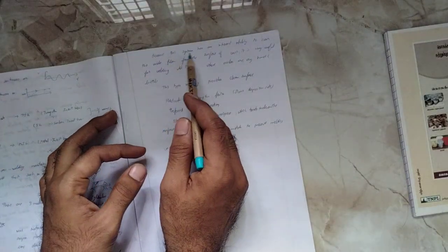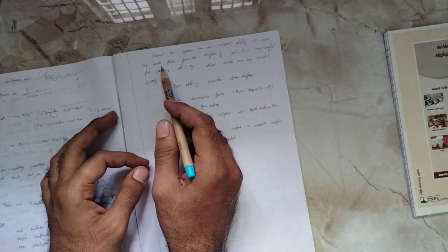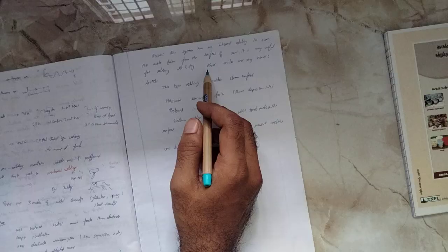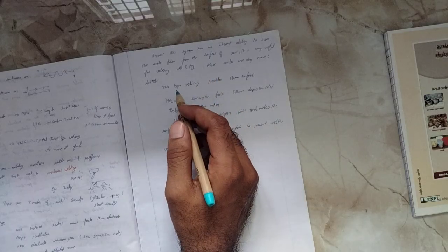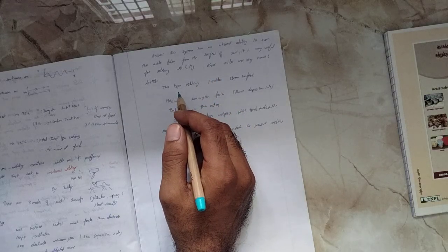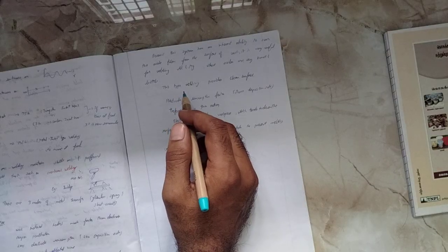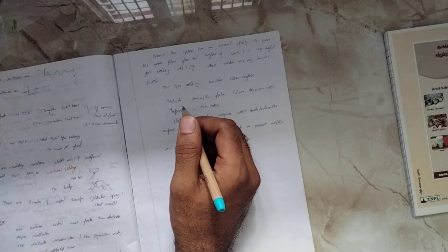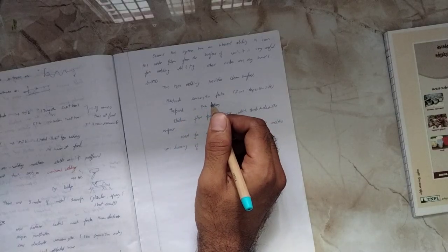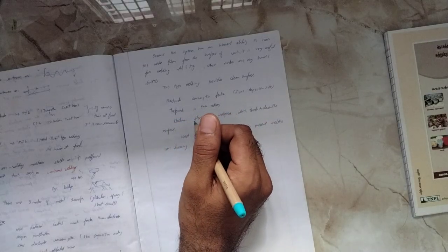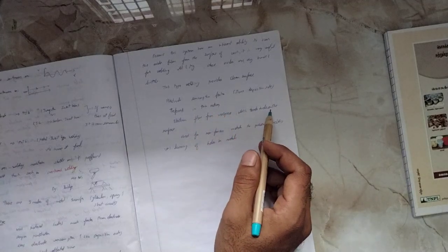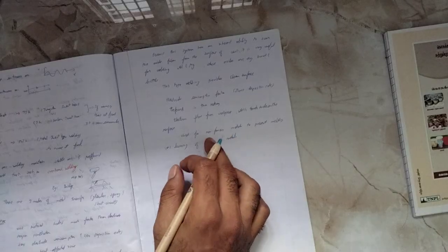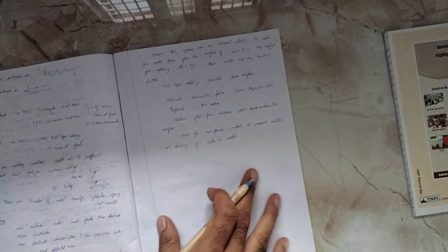Because the system has an innate ability to scatter the oxide films from the surface of the work, it is very useful for welding aluminum as well as magnesium. Where oxides are very hard and brittle, for most of such materials, reverse polarity direct current is generally used. This type of welding prefers a clean surface, has faster electrode consumption, and is preferred in thin sections. Electrons flow from the workpiece and tend to clean the surface, and it is used for non-ferrous metals, not ferrous metals.